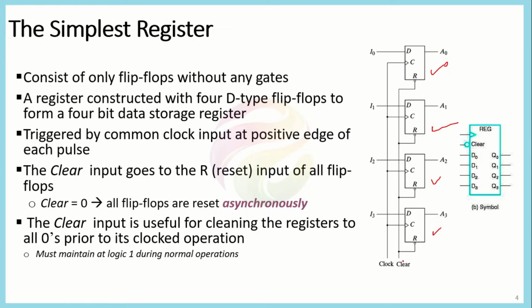We also have a synchronous reset here, which is represented by the clear signal. Whenever this value goes to 0, all of the flip-flops that are connected to it go into the reset state, making all the output values go to 0.